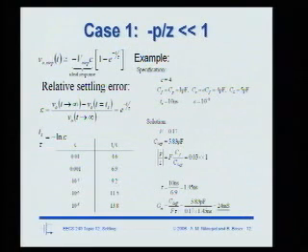It means that this initial 4 or 5 time constants is really necessary in precision circuits to get to the 1% level, but then after that, just a few more time constants gives you a lot more precision if you need it. Okay?